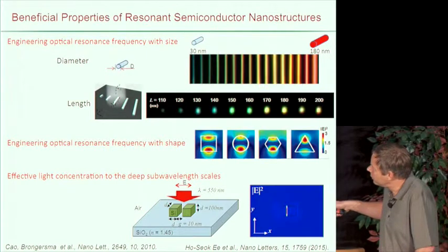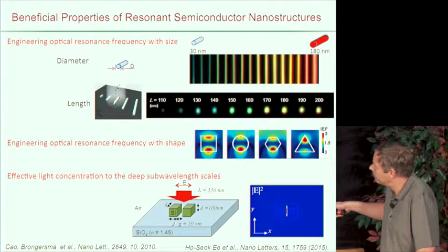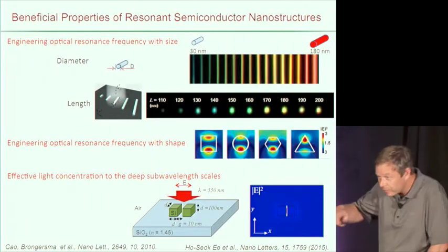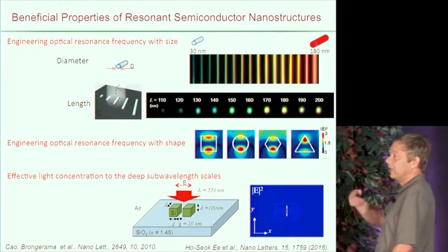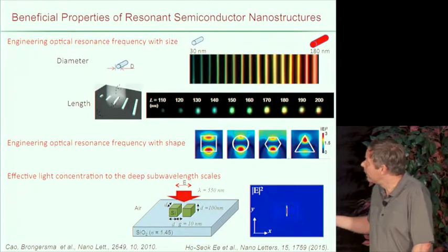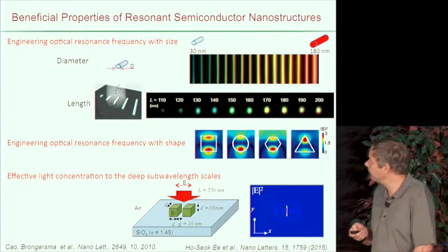And it turns out that any cross-sectional shape, these are beams of silicon, square, circular, hexagonal cross-section, all of these show resonances where effectively the light circulates inside the high-index material, silicon, by total internal reflection, to give higher field intensities inside these structures than around them.